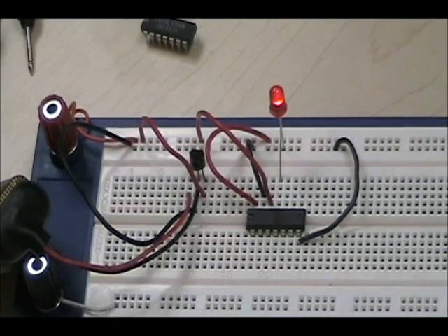So digital gates are very, very simple. You've got to look at the data sheets, find the pinouts, and make sure that you ground everything properly, and you're limiting the power supply to 5 volts. Yeah, just be really careful. I'll show you a couple more. I'll show you the NOT gate and I'll show you the NAND gate, and then that's going to be all for this lesson. Hold on for 1 second.